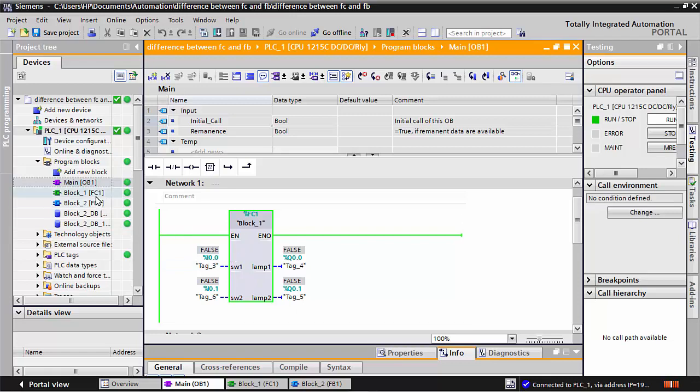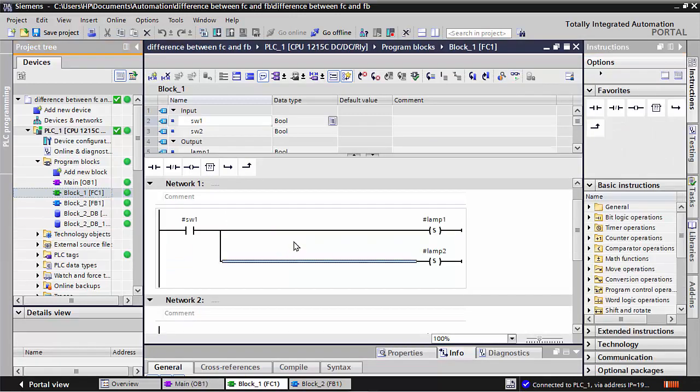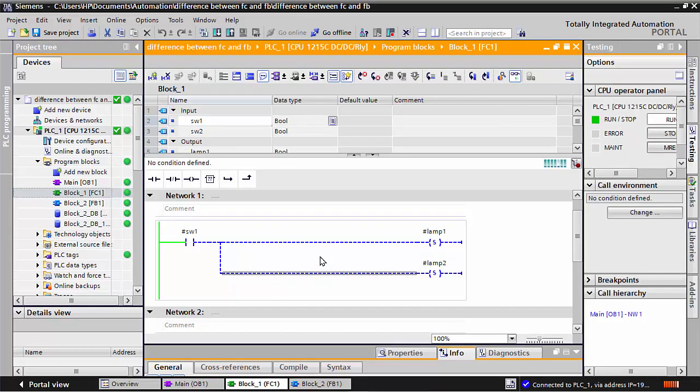Also, if you can see in this area, I will also make it a simulation on the SW1 we defined for I0.0. See, I0.0 is on when I give the signal, but it does not go to set condition because of this command I used for set condition. The signal came, but it is not sent, not set.